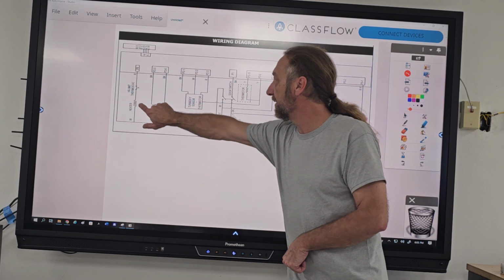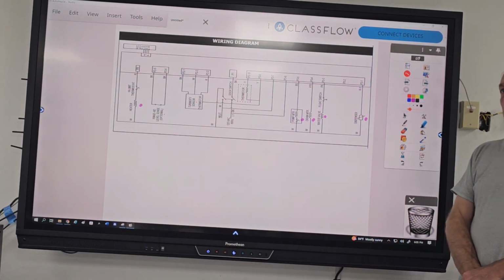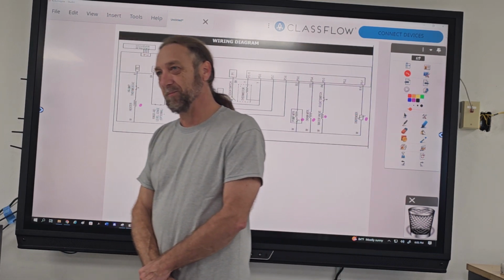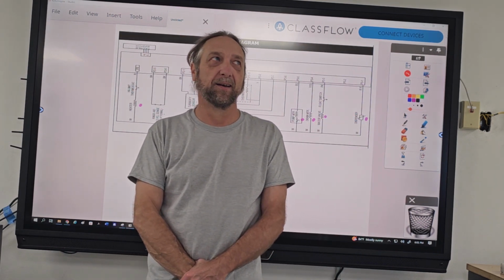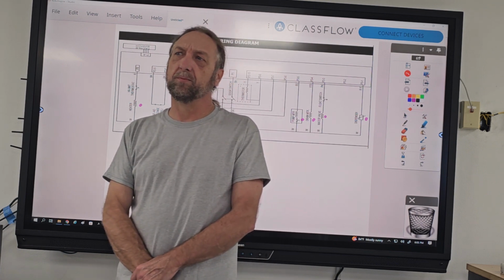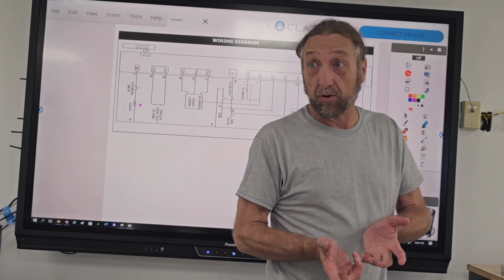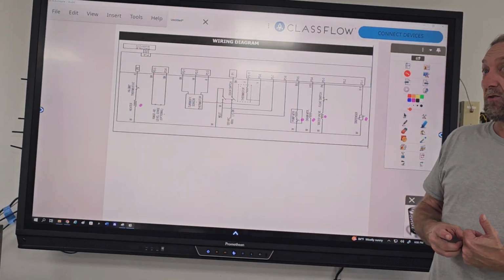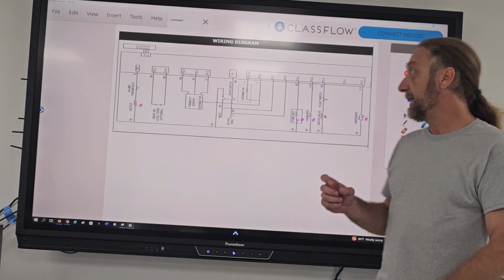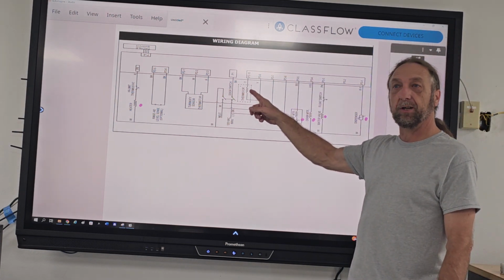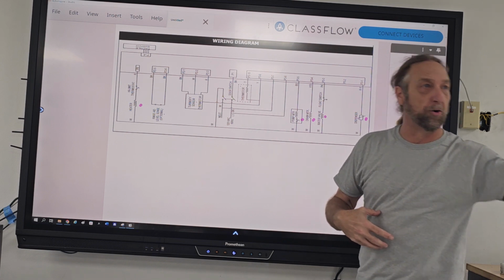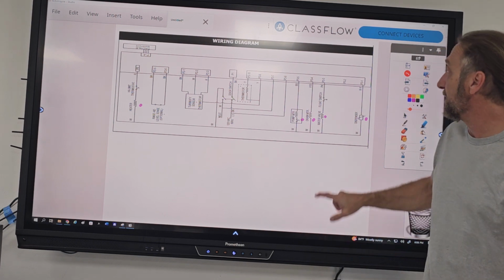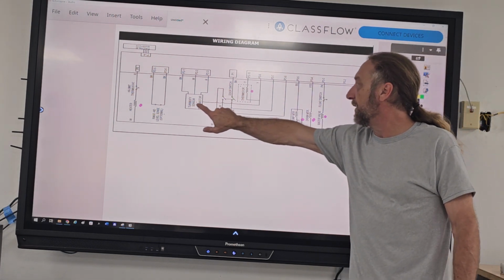The heater. Now, is the thermostat considered a load or a switch? I know it's like a thermostat, but which is it? It's more like a load, with the resistance. It is a resistor that when heated or cooled, the value of resistance changes. So it's more of a load that the board is looking at, and it knows what temperature it is, measuring water temperature or air temperature. So it's a thermistor, and they have one here and also one inside of here.